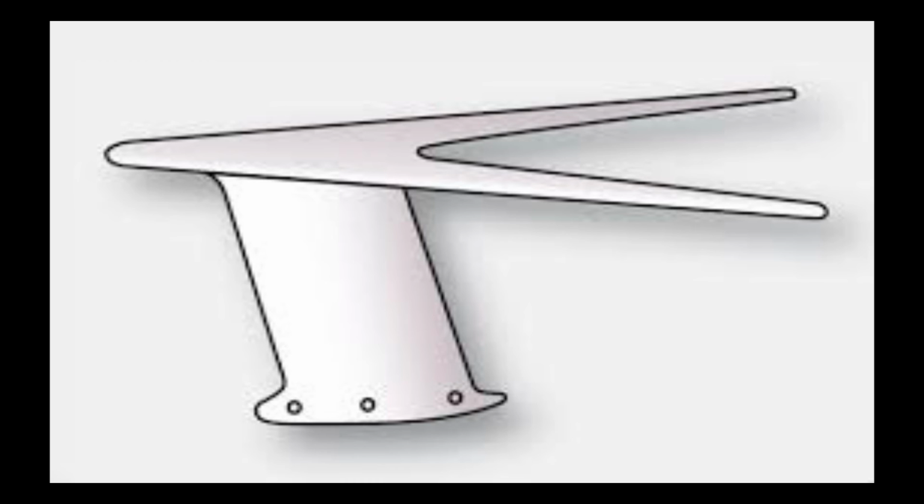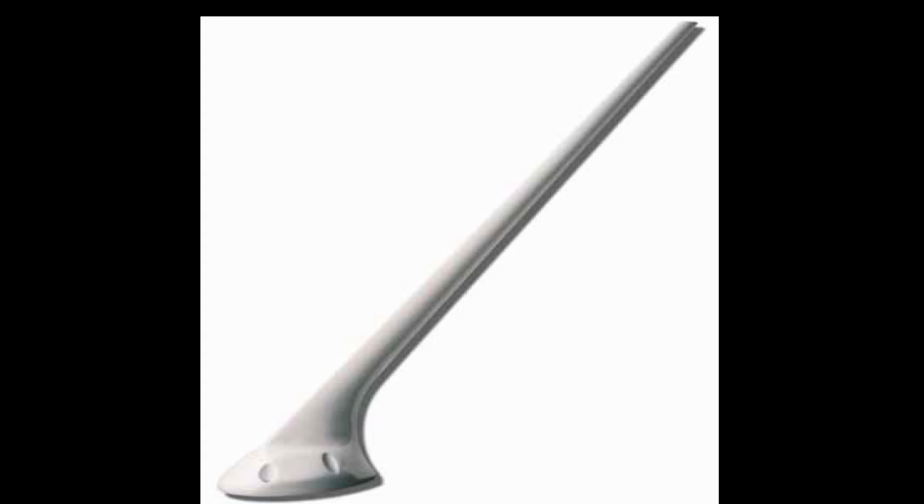Marconi antenna. A Marconi antenna is a 1/4 wave antenna. It achieves the efficiency of a half wavelength antenna by mounting to the surface of a conductive skin fuselage to create the second 1/4 wavelength. Most VHF communication antennas are Marconi antennas. On fabric-skinned aircraft, the ground plate that makes up the second 1/4 wavelength of the antenna must be fashioned underneath the skin.